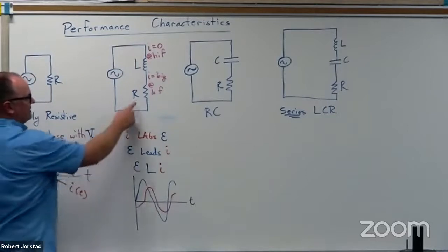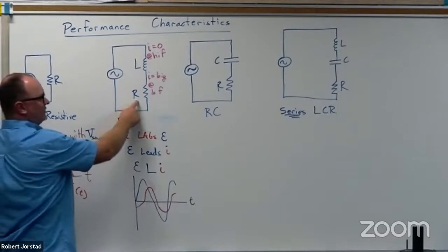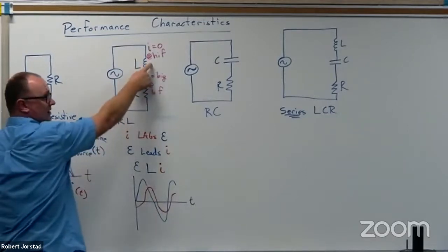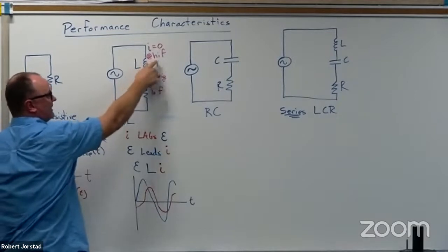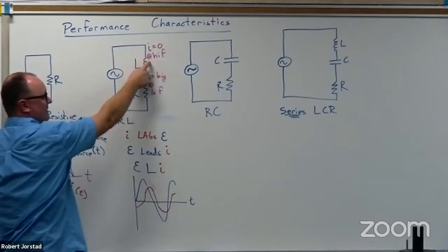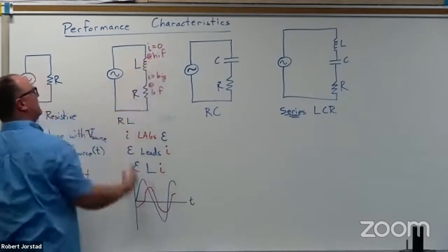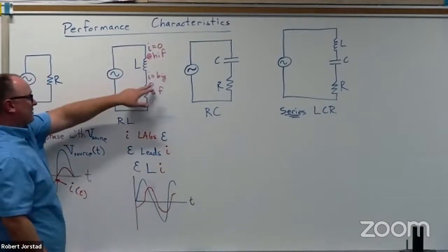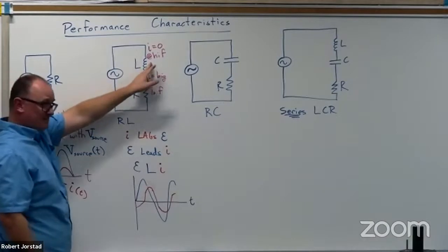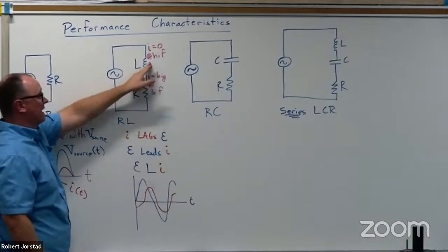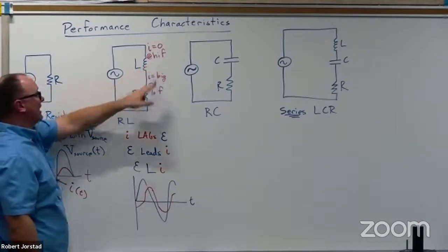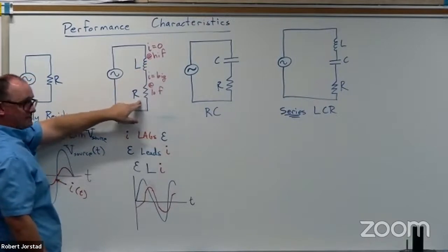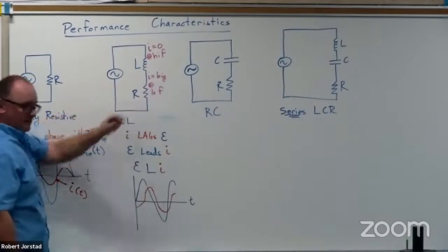So the resistance will have almost no voltage, because when you're changing things rapidly you get a massive EMF, and then you get no current. The other way, if current's changing very slowly, this is basically just a coil of wire. It's got almost no resistance at all, and almost all the voltage will be here. So this makes sense.